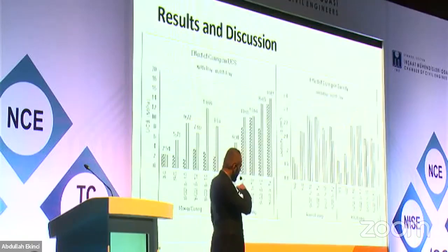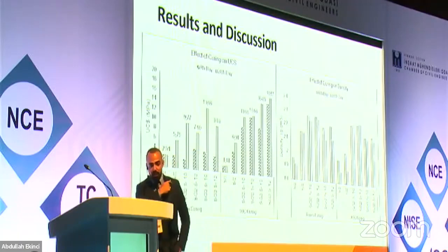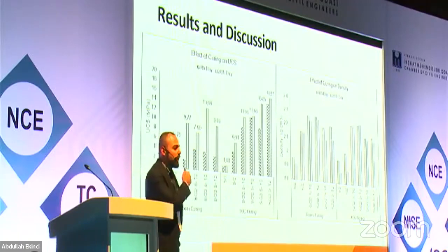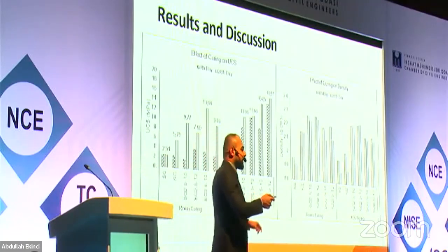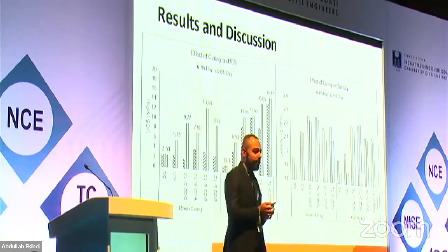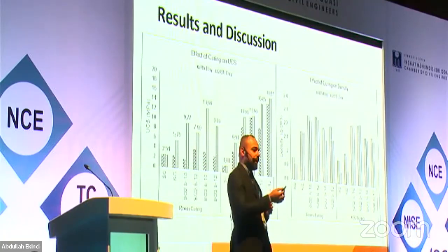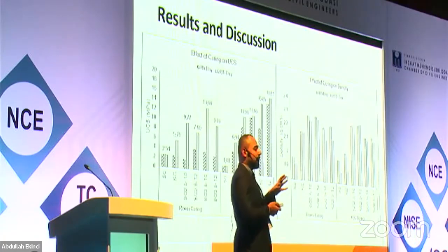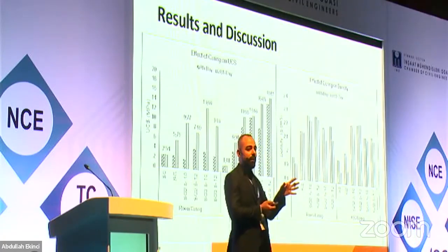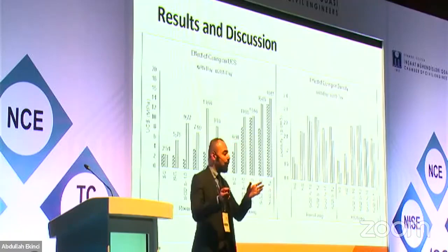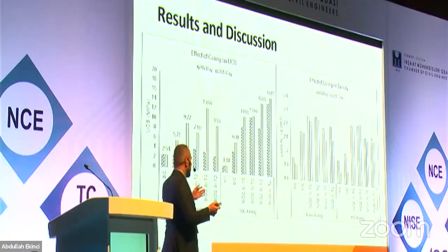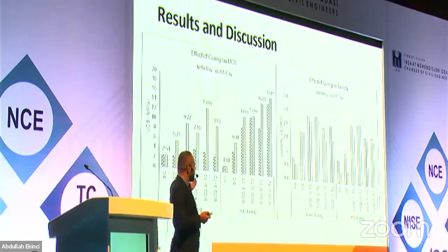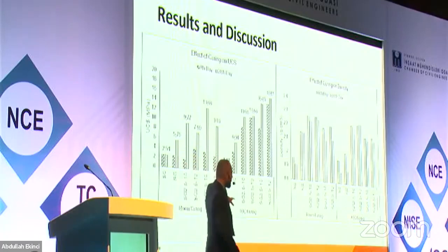So the things that we have here, or I should mention it, we didn't take the unconfined compressive strengths at the optimal moisture content, since geopolymerization requires time in order to gain strength. So the tests that we've done were on exposed samples in the dry condition, at room temperature. We have two of them: one is the room temperature left there for 70 to 80 days, and one in the curing 60.